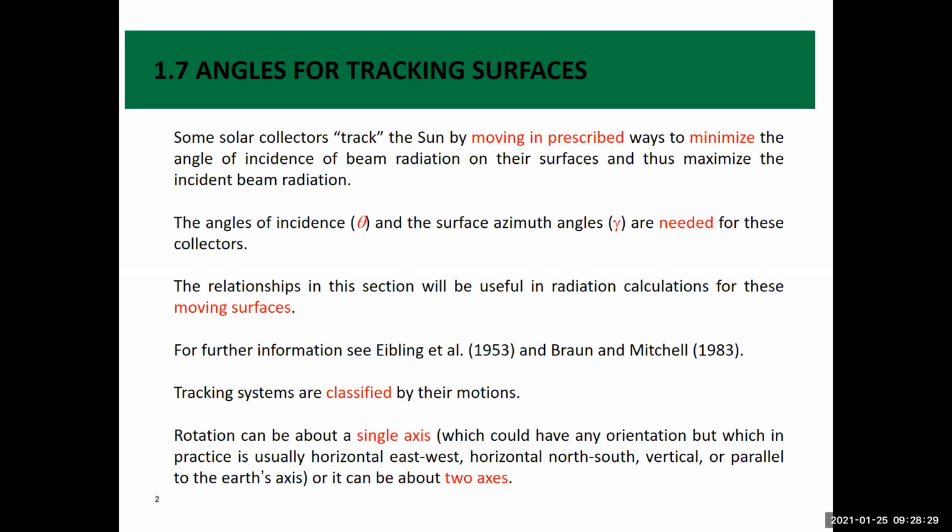What's the benefit? The benefit is that we get more and more energy, because whenever there's a motion of the sun with respect to the earth, again, from the perspective of somebody who is on the earth, then you are following the sun exactly. And this can be done either manually, or sometimes through controls like computer programs that are written and connected to motors. And the motors are moving continuously, minute by minute, so that the sun is in the focal of your collectors, and you are getting as much energy as needed.